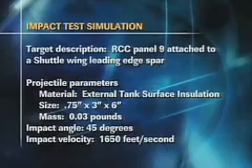The next video, what we're showing here is a simulation using what's called the LS-DYNA tool. This is a computer code that we use to simulate impacts of foam and debris on RCC structures. The tile test program used primarily an empirical approach. That is, we conducted many impact tests on tile material and essentially covered the entire expected or possible range of impact velocities and angles, and produced a series of curve fits that described exactly how the tile would respond when impacted.